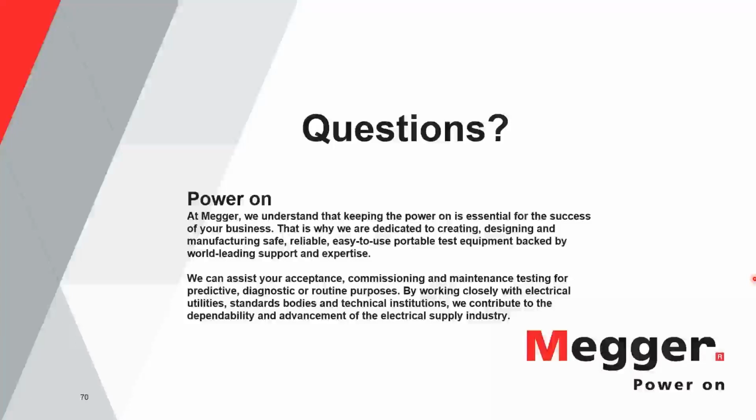So I would say with that one, there's a couple things to consider. It's almost yes and no here, because you can use different testers, but you want to verify a few things. One, that the output voltage is the same. So as long as we have the same output voltage and we're running along the same frequency, they should be pretty much comparable. The only difference that you'll see is also with connections, because say if you're making your connections and one unit's not using the shortest braided ground principle and the other one is, you'll have a little bit of variance there.